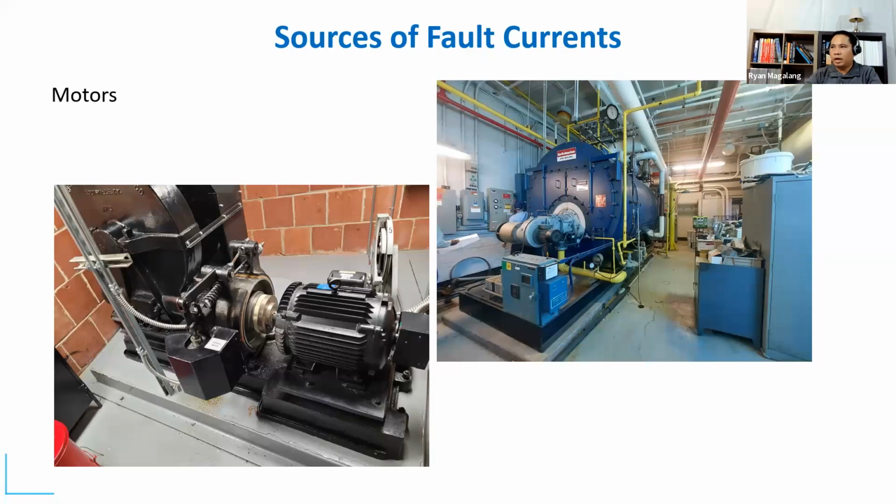One or two motors, maybe not a big deal, but in industrial facilities it's estimated that 80 to 90% of the loads there are motors. So your 1 horsepower motor, your 50 horsepower motor, 100 horsepower motor, they all add up to thousands of amps. So the contribution of motors is important to consider.